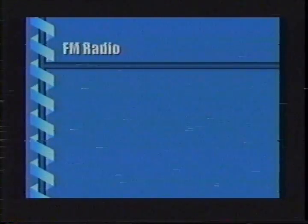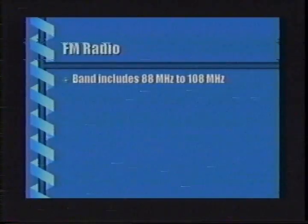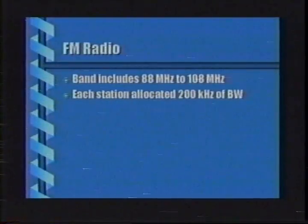Well, let's talk about frequency modulation, FM radio. Here the band is considerably higher in frequency than the AM band. The FCC allocates 88 to 108 megahertz. You might be aware that this is right in the middle of the TV band, television. Each station is allocated 200 kilohertz instead of just 10 kilohertz, 20 to 1, FM versus AM.